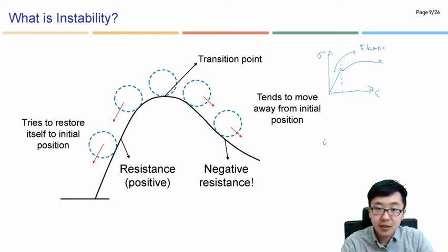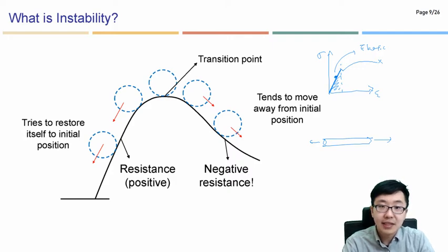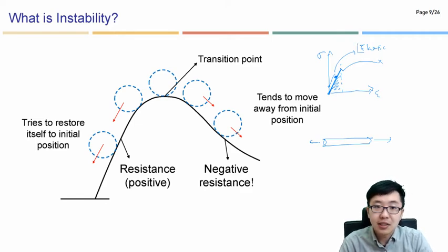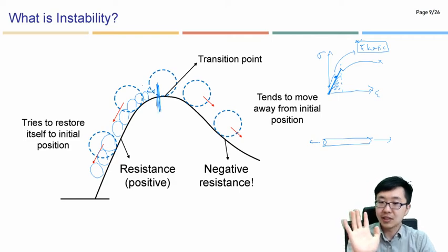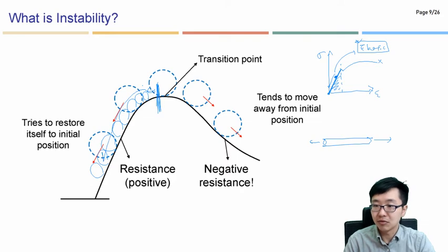If we apply the load, for example tension or compression in this region, once we apply the load till here and then remove it, it will go back to the original status, which means that we don't experience any plastic deformation. That's why we call this the elastic region. So until here, we move our rock and then remove the resisting force, then it will move down to the original place.